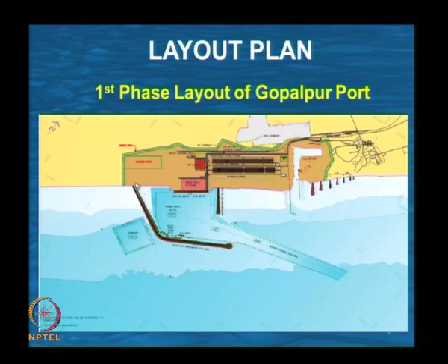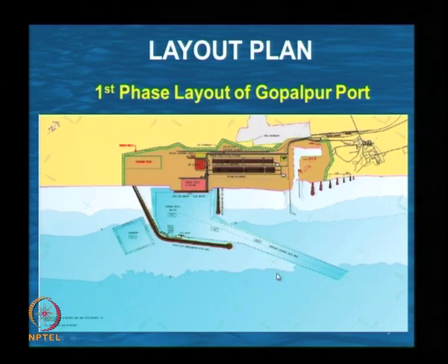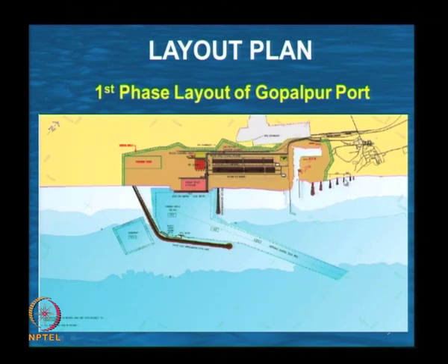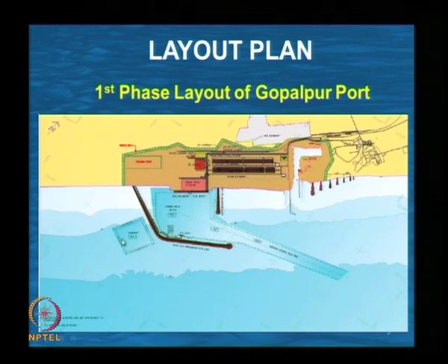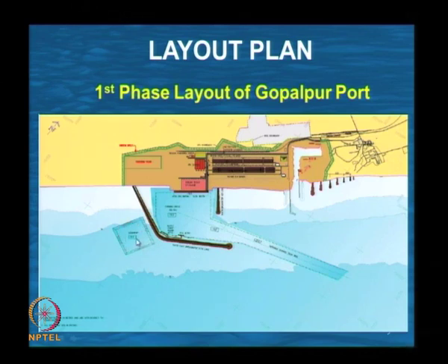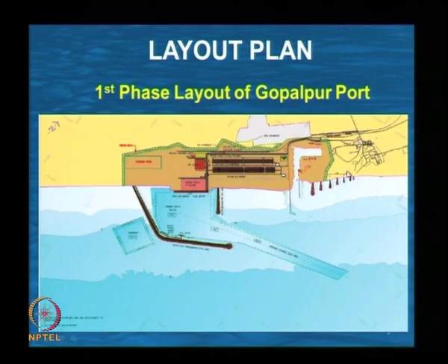So, this is the port that is being built, this is the eastern side. The color code as usual indicates the darker the color, the deeper the water depth. There is one breakwater being built here, the southern breakwater, and this is the northern breakwater. There are a series of groins which are built to reduce the erosion, and this is the channel and this is the harbour basin area where we will be doing the dredging, and this is the area where we use the silt trap or sand trap which will be collecting the sediments, and this is used for maintenance. You remove the sand from here and then dump it on the northern side. That is what we do as an environment management plan.